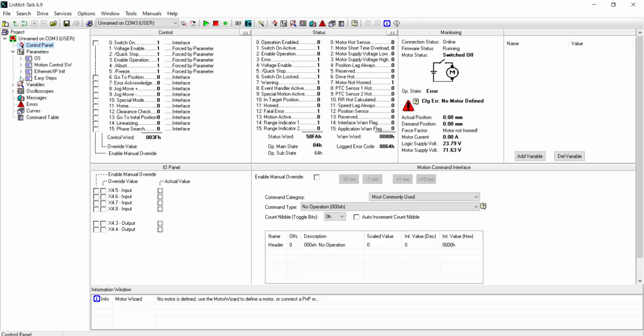There are 3 main parts to the EasySteps application. Those are Smart Control Word Behavior, Analog Parameter Scale, and I/O Motions. The first we'll discuss is the Smart Control Word Behavior. Basically, this allows you to control some of the functions in the LinMot drive without having to use up input pins to do so.